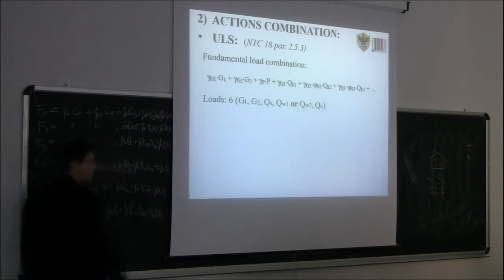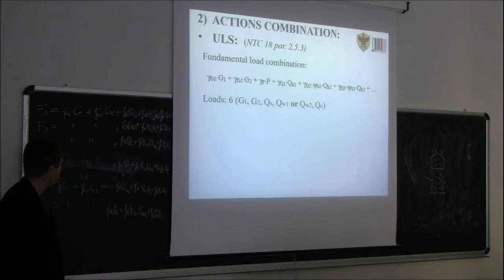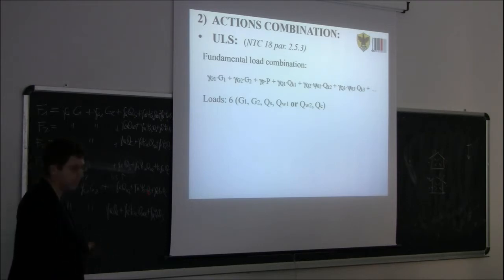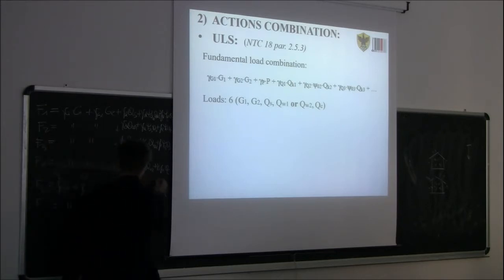And then these other two, gamma Q ranges between 0 and 1.5. So QS and QC, how are they oriented? Are they uplifting or are they downward? Downward. So it means that which value of gamma Q here and here? 1.3. No, gamma Q is between 0 for favorable to 1.5 for unfavorable. So is QS favorable or unfavorable? 0. So 0 and 0.